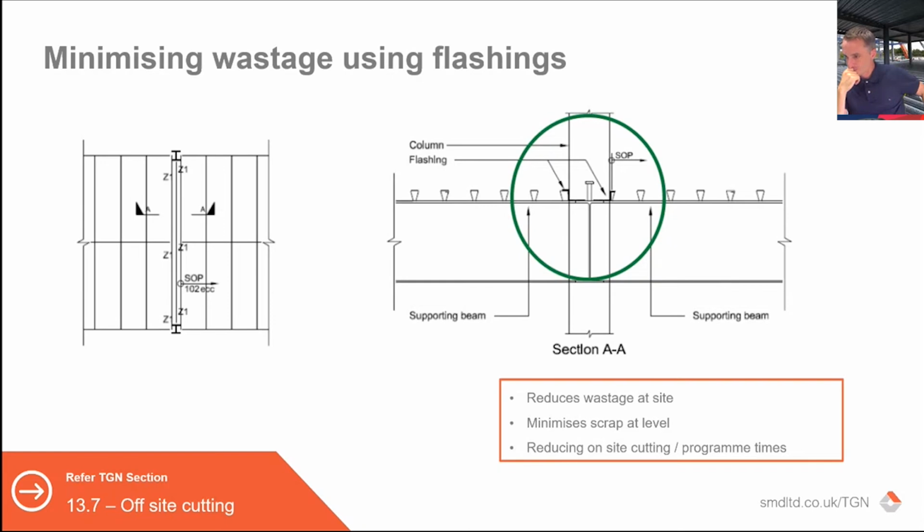I think what Bob's asking is, can it damage the coating? I don't know if Bob's had any instances where it's happened to him. I wouldn't say it couldn't. It comes down to the thickness of the flange again, because it's displacing steel. Obviously, the thicker the flange, the less effect it will have on the underside of the flange. I wouldn't say it couldn't, but it's not something I'm aware of in my experience, which is quite a long time. I'm getting older.